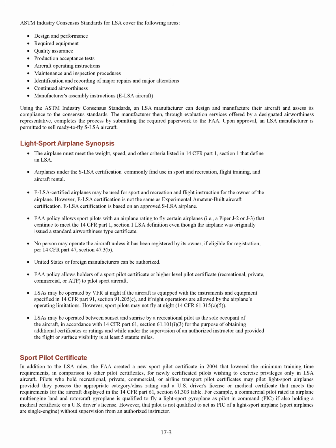Using the ASTM industry consensus standards, an LSA manufacturer can design and manufacture their aircraft and assess its compliance to the consensus standards. The manufacturer then, through evaluation services offered by a designated airworthiness representative, completes the process by submitting the required paperwork to the FAA. Upon approval, an LSA manufacturer is permitted to sell ready-to-fly SLSA aircraft.